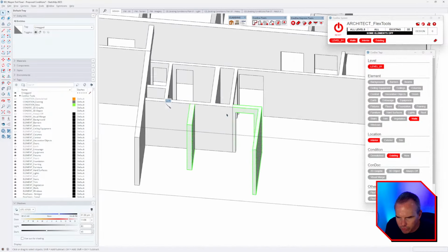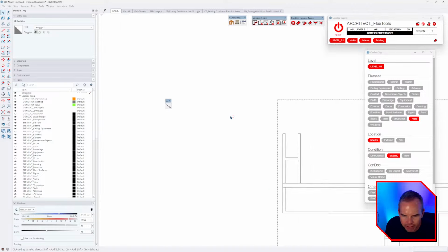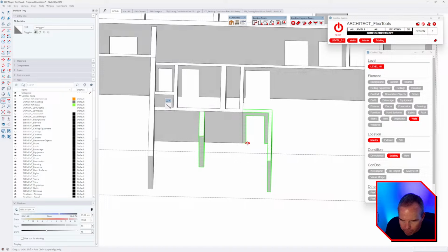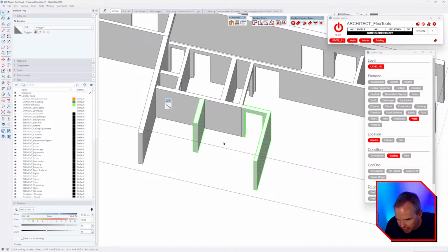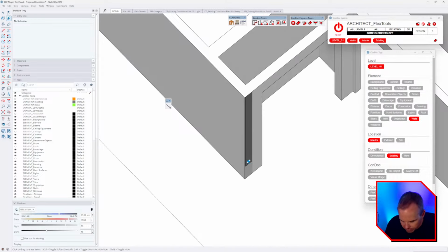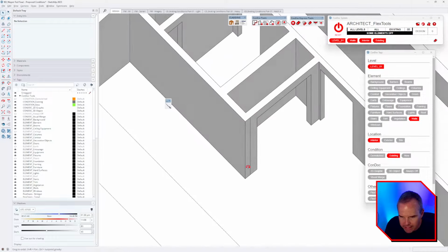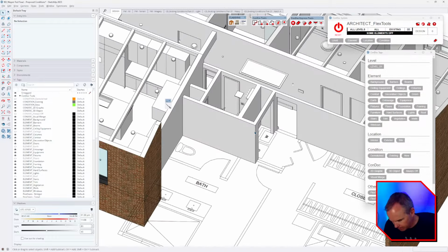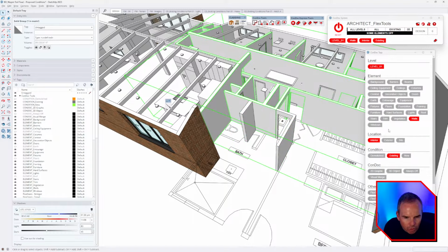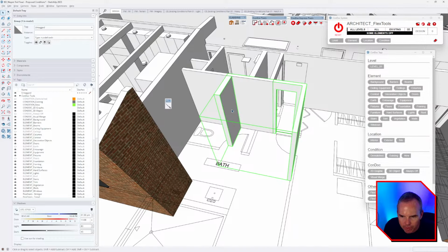All right, so then let me look at it from above again. I need to make a better selection. So we're going to go real close to that wall, and that way we got all that stuff there. And then I can group it, I can cut it, and then I'm going to patch these walls with my line tool like that and like that. And then I can back out of here and I can do a paste in place. All right, so remember these are level 1 walls interior existing. These guys are going to be level 1 walls interior demolished.